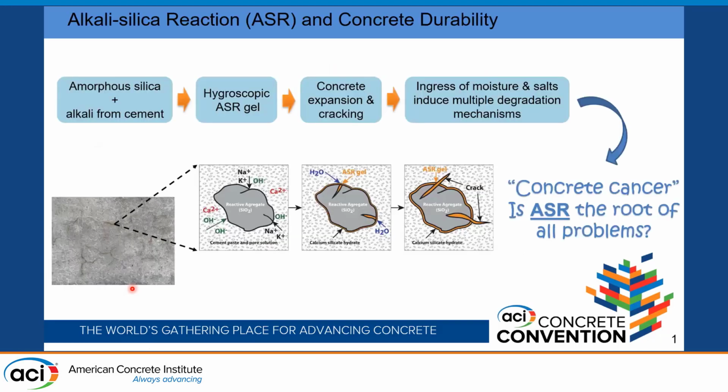It's well known that the alkali-silica reaction is a reaction between the amorphous silica from the reactive aggregate and the alkalis from cement. The result of this reaction is the formation of the hygroscopic ASR gel. This ASR gel can absorb moisture and water to have volume swelling inside the concrete. So this can result in the concrete expansion and cracking.